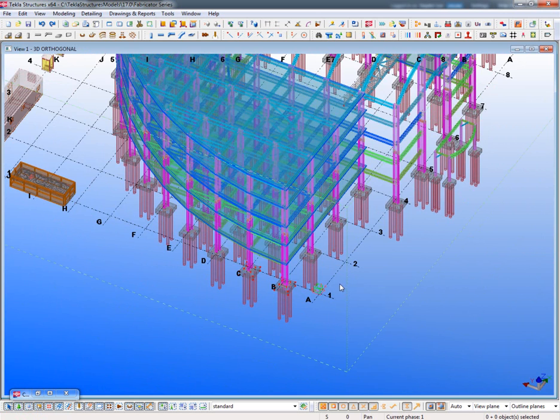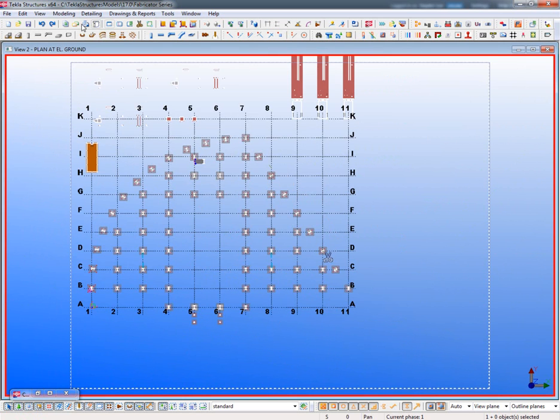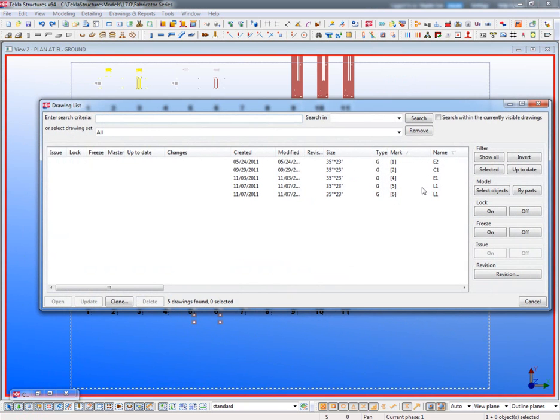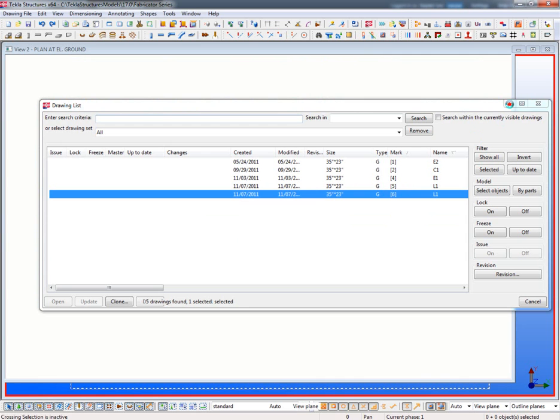Yeah, I mean, it's worthwhile mentioning as well, in every single contract that we've ever seen, the fabricator has to verify the anchor bolt positions prior to fabrication. You have yet to see a construction contract without that verbiage in it.